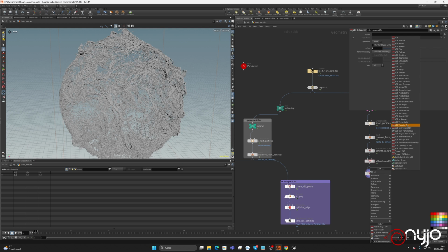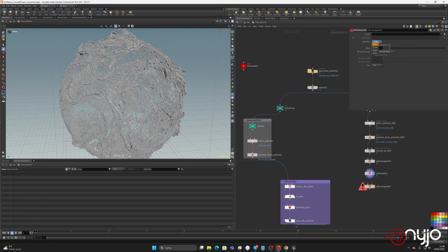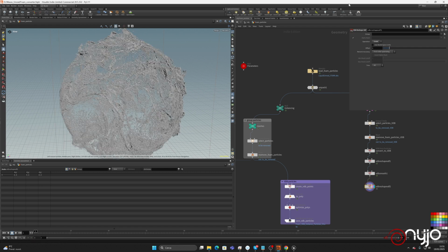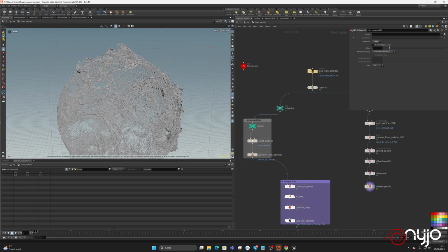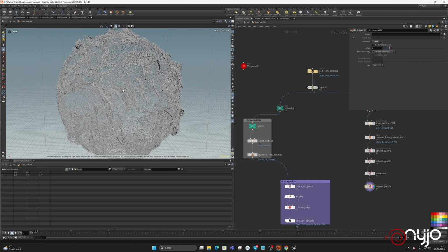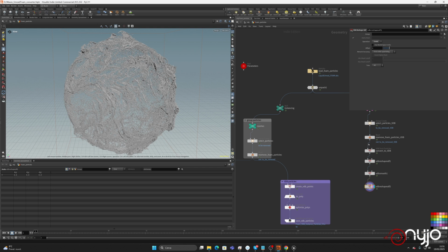Let's go back to another reshape, and this one can be set to erode, and we try to erode a little bit everything. So let's say set to manual, connect, activate this one, and then update, and let's see what's going on. Okay, you see we've done something, because now we created the erosion, so we have something that is more similar to the foam. So that's something you can do, and again, we can play more with VDB reshaping and stuff like that to achieve something that is higher quality.